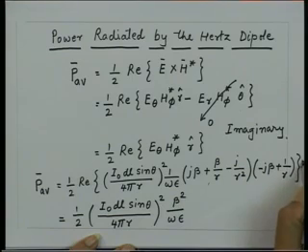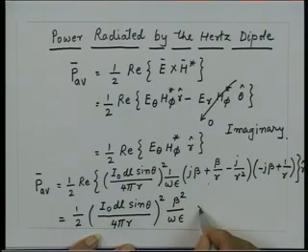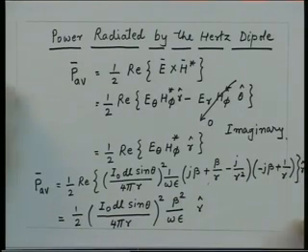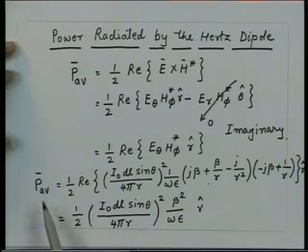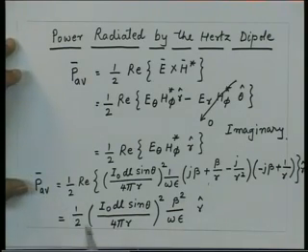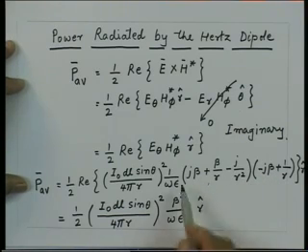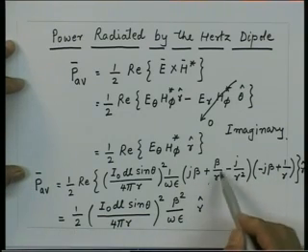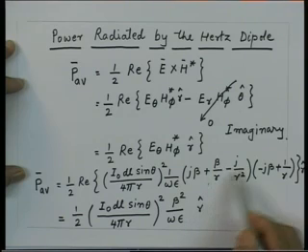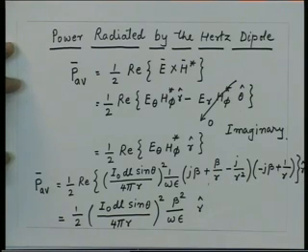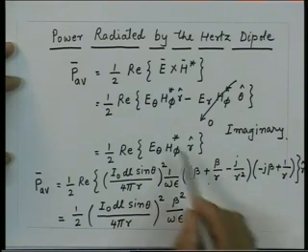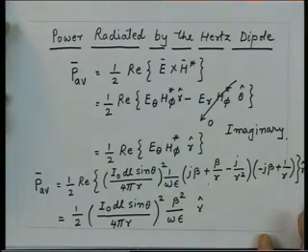and this will be in the direction r. So, it has the unit vector r. So, this also will be in the direction r. So, what that means is that the power Poynting vector which we have, which gives you the power density, that is only coming from these terms which are related to the radiation fields. Other terms which are having a variation as 1 over r or 1 over r square, these terms they do not have a real contribution to the power flow.